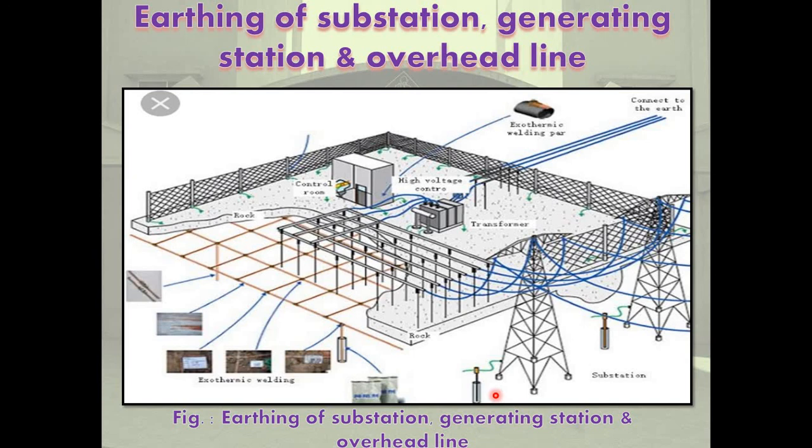If earth resistance is high, what actions should be taken? Clean the surface of the earth electrode, and mix the soil in the earthing pit with charcoal, salt and soft soil mixed together. Pour sufficient water in the earthing pit. Connect the earthing rod with the help of equipment and a low resistance copper strip, and use a larger number of electrodes and a larger base.